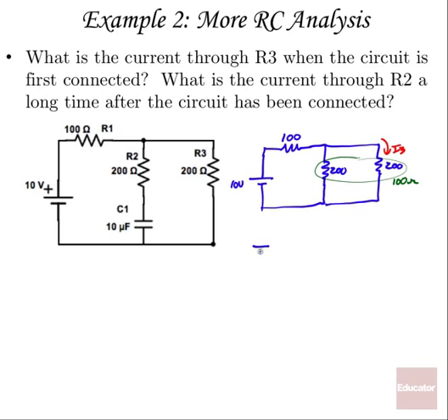We've got 10 volts from our power supply. We've got 100 ohms and 100 ohms, and a nice simple series circuit. Well, it should be pretty easy to see if that's 10 volts and we've got two resistors right between them here, we must have a voltage of 5 volts.